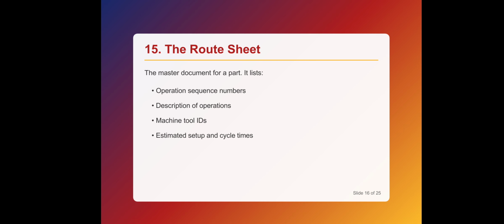It provides information like part identification numbers and names, description of the processing steps in each operation, operation sequence and machines, standard setup and cycle times, tooling requirements for each operation, and production control information showing planning lead time at each operation.